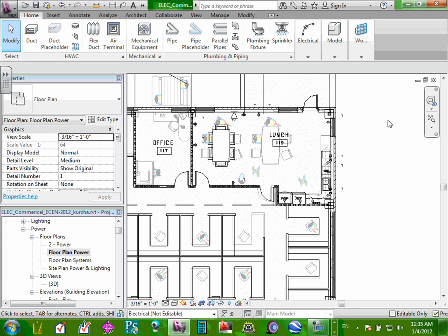So they want the lunchroom vending machine and the lunchroom refrigerator and the lunchroom microwave on a dedicated circuit. Good idea, because these are major equipment. Did you guys see why? See that note number 6 next to it? Provide a dedicated circuit. So these are solved, done. I don't need to mess with them. Let's look at number 1, lunchroom coffee. Coffee pot doesn't say anything about a dedicated circuit for the coffee pot.